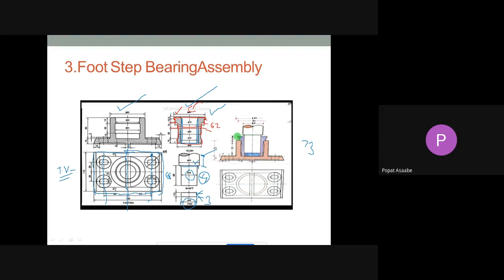बरोबर. Then also we can take the center point of this portion. Okay, center point आपण काढून घ्यायचं. Just we have to divide the 115 and draw this center point. Okay, center point आपण ड्रॉ करून घेतलंय. त्यानंतर बघा, the gap between that two lines also we have to take. किती गॅप असेल या दोन लाईन मधला? Yes, 5 mm, because they have given it here. See, this 5 mm gap they have given, so I'm going to take the 5 mm gap and draw this line.